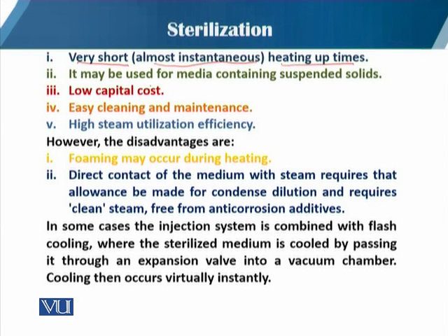So it may be used for media containing suspended solids. As compared to the previous method, it involves a low capital cost. In this, there is easy cleaning and maintenance, and high steam utilization efficiency. However, in this case, there are disadvantages. The first one is that foaming may occur during the heating.